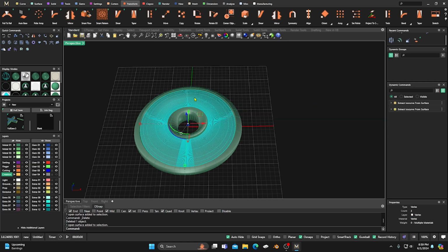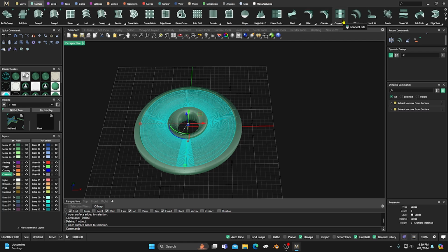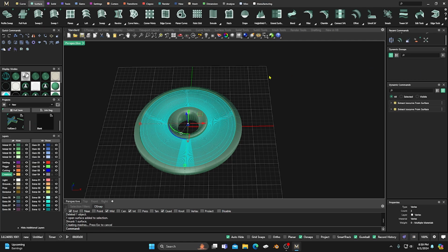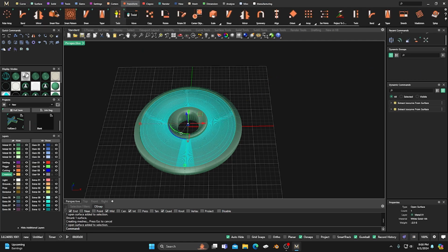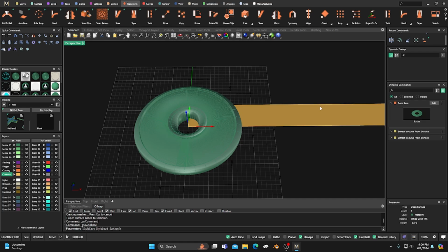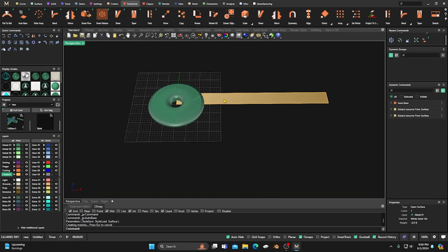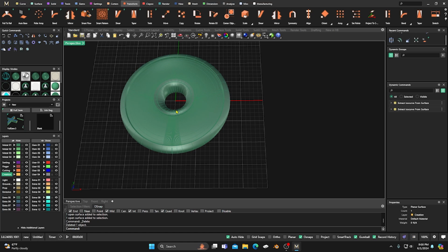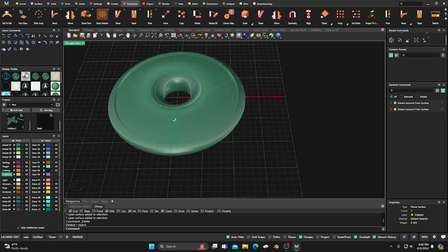So what we need to do is select this surface, go to the surface menu and scroll down to edit tools, and we want to shrink trim surface and hit that, right? And now if we were to do that auto base, so let's go back to auto base, you can see that it's a much thinner item, right? And this right here now is representing just this surface, not the entire item, and that's what we want. So if you're doing auto base or something like that, and you're going to do a design on your own, be aware that you'll probably need to shrink trim surface, right? But we're not going to.